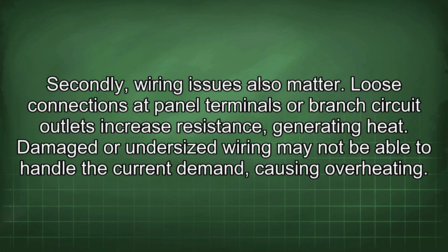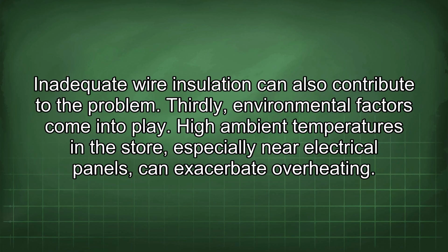Secondly, wiring issues also matter. Loose connections at panel terminals or branch circuit outlets increase resistance, generating heat. Damaged or undersized wiring may not be able to handle the current demand, causing overheating. Inadequate wire insulation can also contribute to the problem.